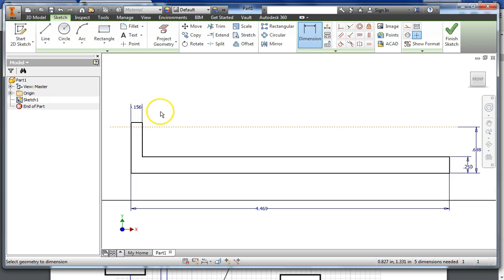So let me turn the dimension tool off. I don't want to dimension right now while it's above. I'm going to grab this while I can still move it and bring it underneath, and then I can dimension that distance and it will know that I want it to be underneath. And the distance I put here, we're going to need to think about.